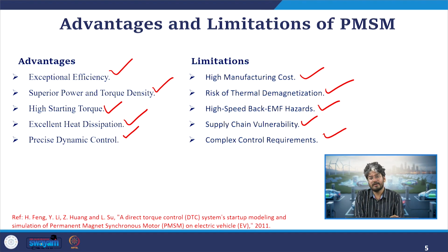When we supply the AC source for the first time, if I know where the north pole or the south pole of the rotor is located inside the machine, or at what point I have stopped the vehicle, I can directly apply the AC voltage such that an opposite pole is developed nearby, torque is generated and our rotor starts moving. Because of that we require the absolute position or the actual position of the rotor circuit. So we will have a complex control design.